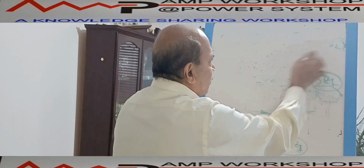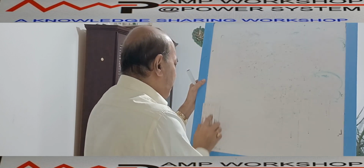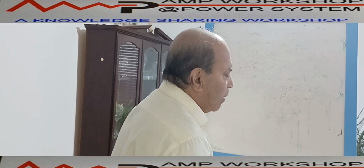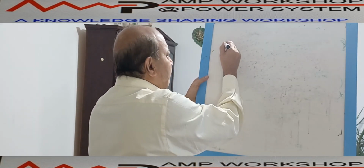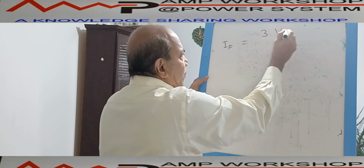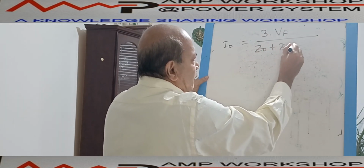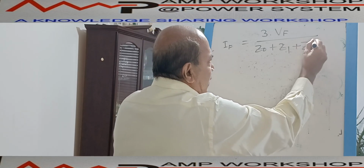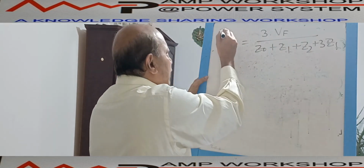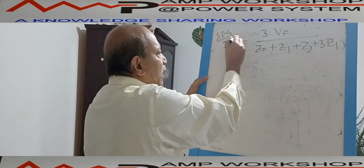When there is a single phase to ground fault in a 3-phase balanced system, what will the single line to ground fault current be? Single line to ground fault IF equals 3 times the fault voltage, 3 VF, divided by zero sequence impedance plus positive sequence impedance plus negative sequence impedance plus 3 times the neutral path impedance. That will be the expression for single line to ground fault. This is the formula.